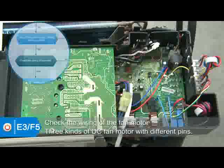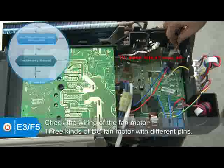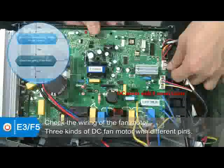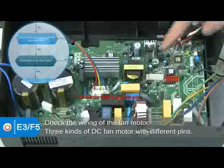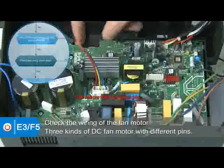Commonly, there are 3 kinds of DC fan motors with different pins. First, DC motor with a 5 cores pin, which has a control chip inside itself. Second, DC motor with 2 pins, 3 cores pin and 5 cores pin. The control chip for it is on the main PCB board. Separately, 3 cores pin connects to the power supply, and 5 cores pin is used for signal transmission. The third, DC motor with a 3 cores pin, which has the control chip in itself.